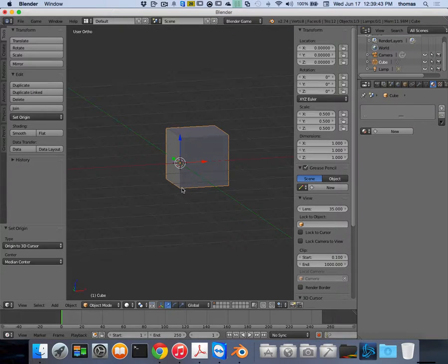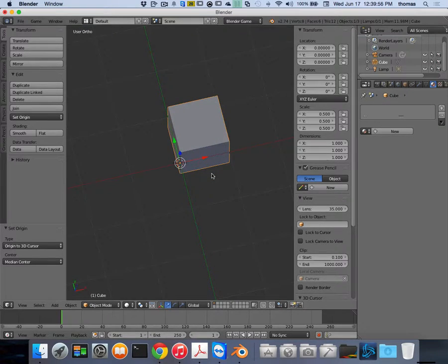In order for me to get that, I'm going to transform it again. So I don't just want it in the middle of these two faces. I want it right here in the bottom, in this vertex. And to be exact and accurate, I'm going to go to front mode. There's my front mode, and I'm going to pop this up half a Blender unit in the Z direction. So 0.5. It moves up half a Blender unit.